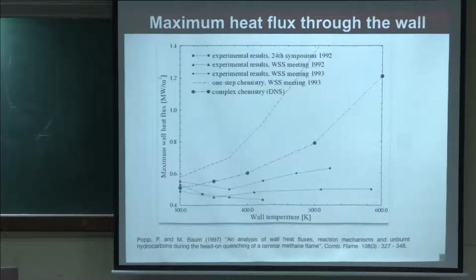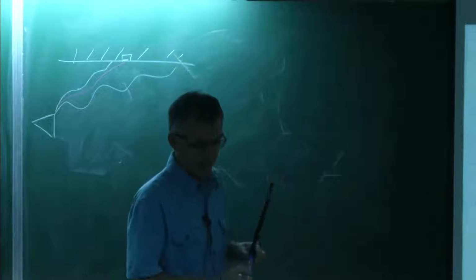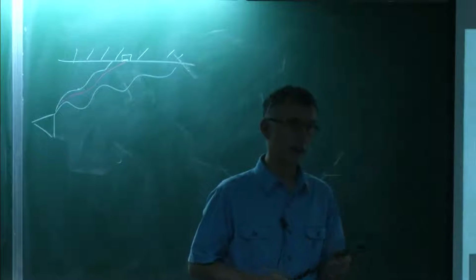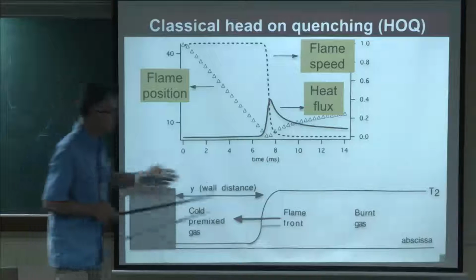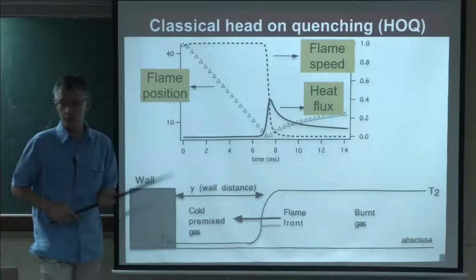It's not so interesting to look at this result that way. From a theoretical point of view, what should be useful is to scale them. And that's what's been done, actually. There's one quantity which is relevant for a problem like this, which is the power of the flame. The power of the flame is the quantity we should use to scale the fluxes. It's obvious that if you have a very energetic flame, you're going to generate a higher flux.